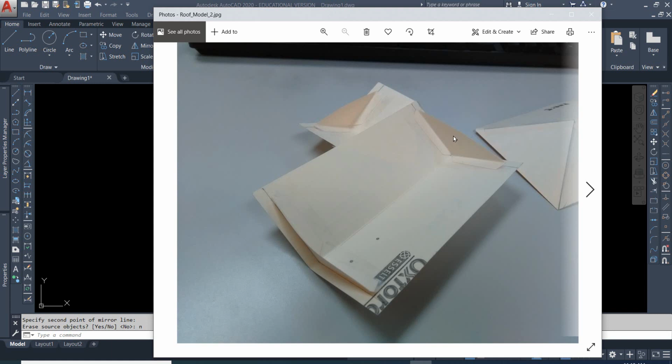That would go right here. And if you notice, looking at the models in the lab or at the photos here, I put little tabs, an additional quarter of an inch or so of material, so that I can fold it over and give me something to tape with. And when it comes time to folding these things, if you'll take your architect scale and set it down and then lay your cardstock on top of it and push down on top of the scale, it gives you a nice clean edge that you can use to bend your paper over. Just a little tip there to help you.